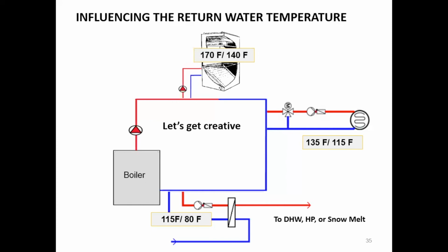One that comes up quite often is domestic hot water preheating, where we'll do a bank of indirect water heaters as the water heating source. But then we'll add a plate heat exchanger in there, and we'll use the return water coming back from the coils and the indirects to preheat the incoming domestic water. And let's open that up. But again, in an application where I'm designing from the ground up, a lot of times I can do something like this to open up the delta T's to get the return water temperatures down lower.